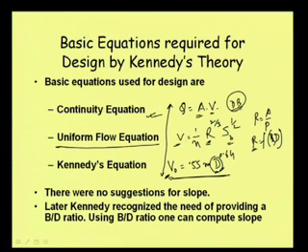We can use Kutter's equation also, but as it is very lengthy, I am just writing Manning's equation here. We can use it to get V. For our requirement, we are considering this to be the critical velocity, but when we calculate using the uniform flow formula, after getting b and d from this continuity equation and Kennedy's equation, we will get another uniform flow velocity.